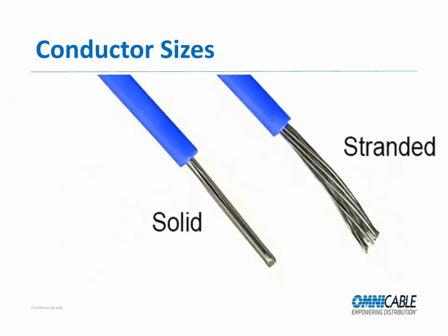Both solid and stranded conductors follow the same standards. As we have already seen, stranded conductors are slightly larger in terms of overall diameter because of the gaps in between individual strands. However, those gaps are not measured when calculating the actual gauge from the area of the conductor. So a 2-gauge solid cable may appear to have a smaller diameter than a 2-gauge stranded cable, but they really are measured and classified as the same size.